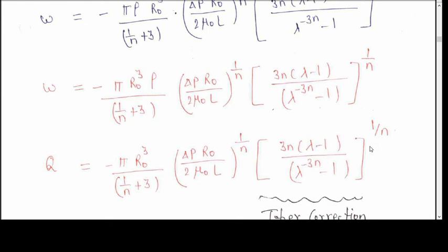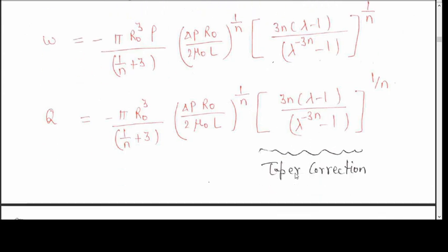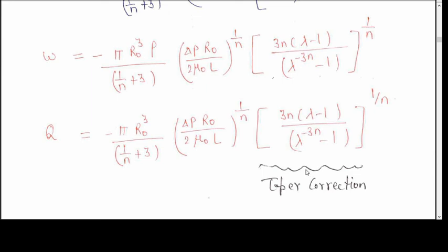Now, this particular term inside the bracket is known as the taper correction, and this equation is valid for flow of a polymeric fluid in a slightly tapered tube.